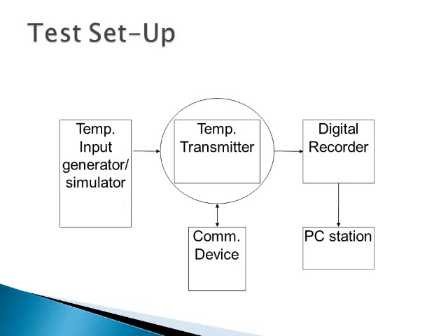So what you have is a test setup, a very simple setup. We did it for a temperature transmitter. So temperature simulator, there are very good temperature simulators by Fluke and many other companies. So we inject that temperature. We can inject for RTD very precise ohm values. For thermocouple, we can give millivolt values.